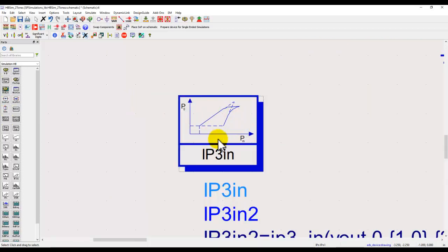And this is a representative picture. How do we compute these IM products? If you take a linear gain slope of the fundamental and keep extending it to infinity, for example, and then take the corresponding intermodulation product like the third harmonic or the second harmonic, and take its linear slope, wherever they intersect, if you look at the y-axis, that's where you get the IP magnitude.